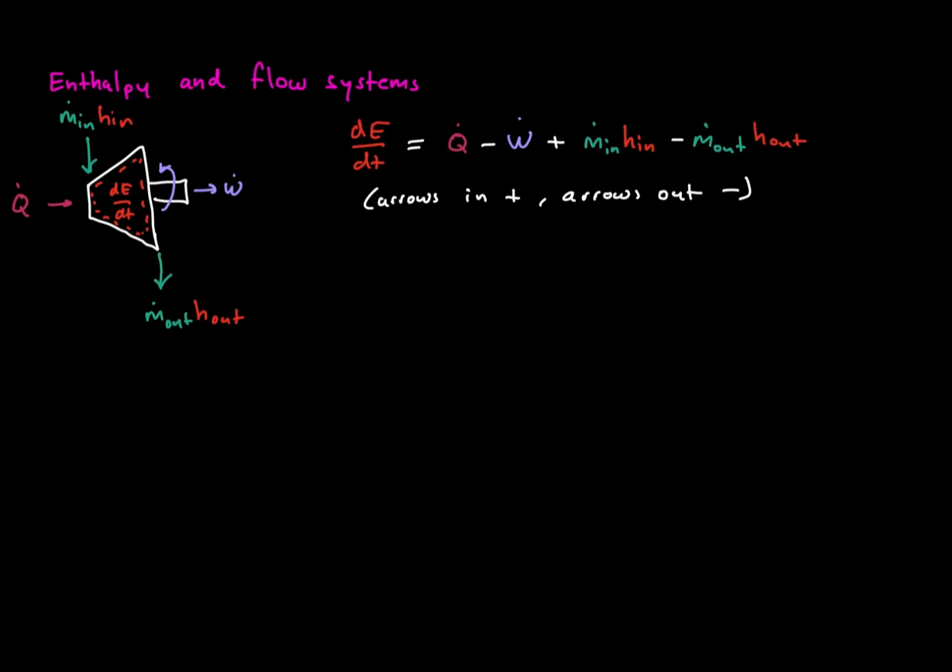So far, we looked at closed systems like a piston, but most real engineering systems are different. Fluid flows through them. Think of turbines, compressors, or pipes. Now, energy does not only enter as heat, it also comes with the flowing fluid. Let's start from the general energy balance.